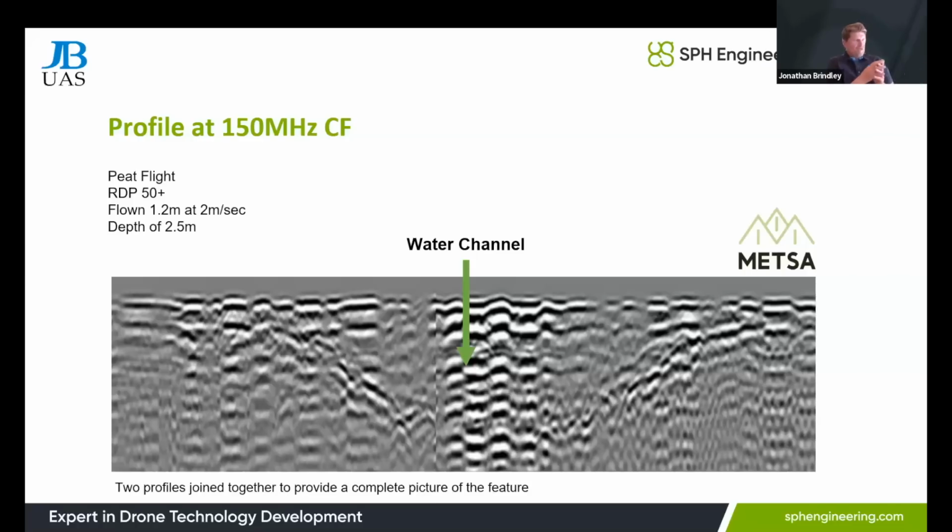But certainly from what you can see there, we mentioned dielectric contrast before, where you have a difference in conductivity between two materials. In this case, it's peat, and below it will be some mineral. It could be rock, rubble, and you can clearly see the dielectric contrast, the difference in conductivity, and where that difference is seen. That difference is seen where you can see the dark lines that move down towards the bottom of the picture and then move back up to the top again.